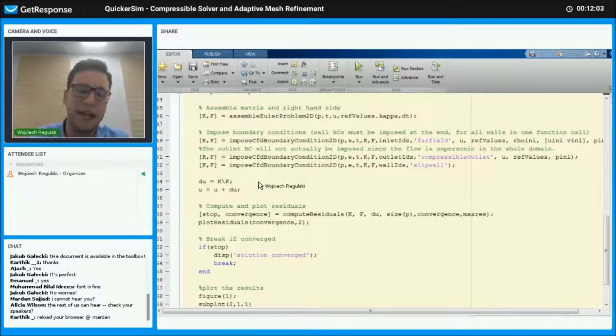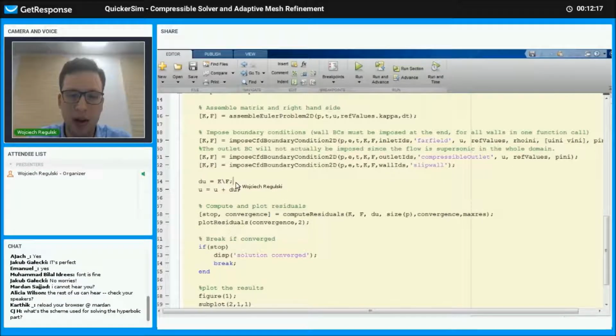Basically, if you solve for the increment in the specific finite element volume formulation that we use here, the stiffness matrices that you get have a lower conditioning number, so they're simply faster to solve, especially when using iterative solvers. But we'll talk about that in a second.